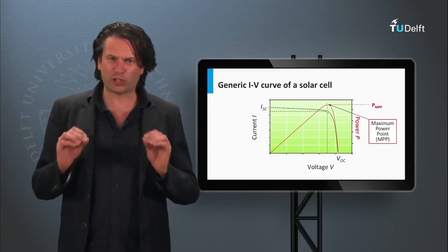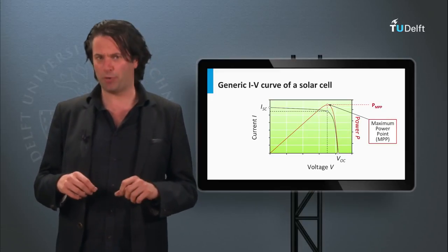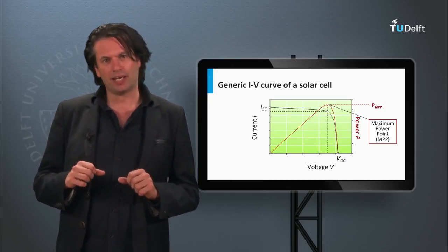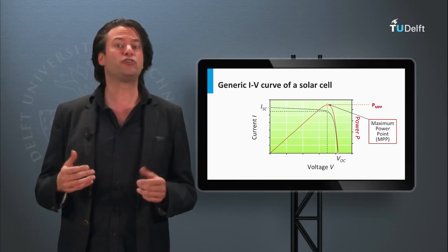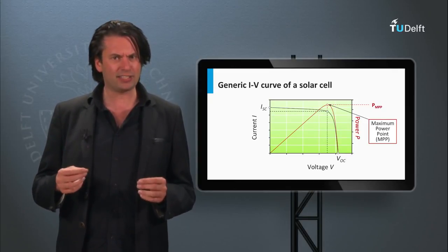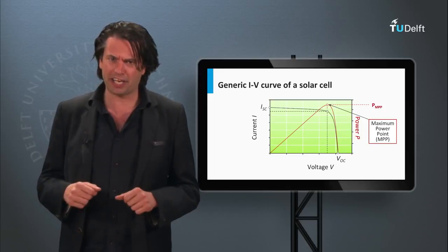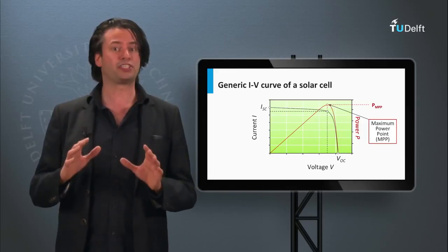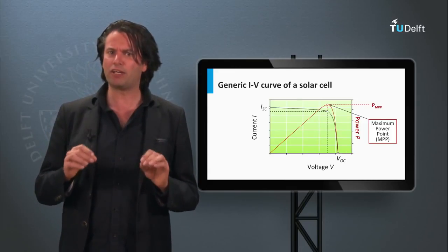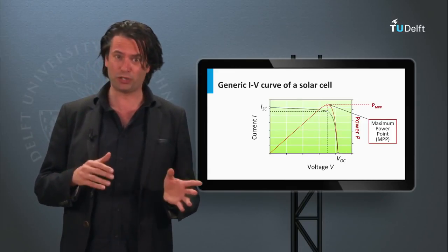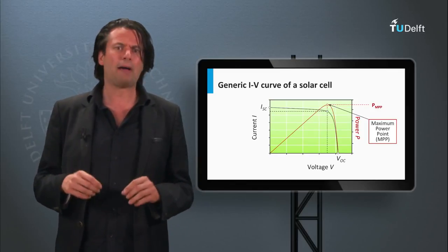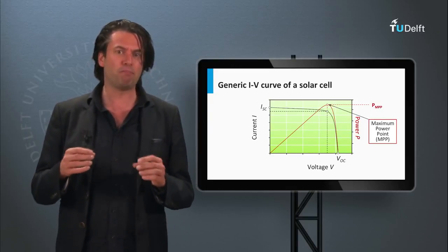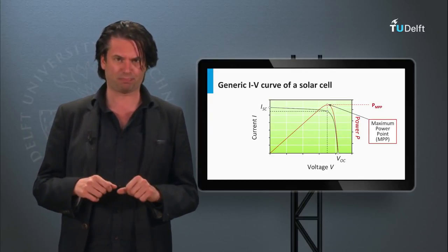In this blog, I will discuss the concept of maximum power point tracking, or as is commonly called, MPPT. This concept is very unique to the field of PV systems, and this also brings about a very special application of power electronics in the field of photovoltaics. The concepts discussed in this blog are equally valid for cells, modules and arrays, although maximum power point tracking concepts are usually employed at PV module array level in practice.